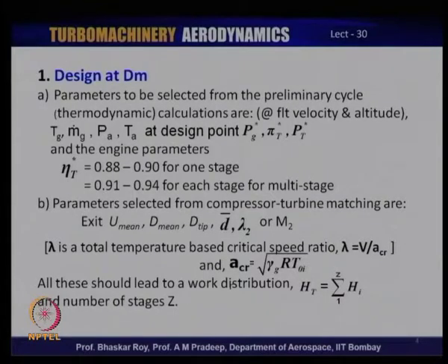Depending on the state of art of the engine design, some of the efficiency parameters can be aimed for, and to begin with, some efficiency value needs to be used for design purposes. This would indeed have to be checked out later on through detailed analysis. So, the efficiency values given here are kind of ballpark figures that one can use to start the design process. If it is a single stage turbine, quite often efficiency of the order of 88 to 90% is often possible.